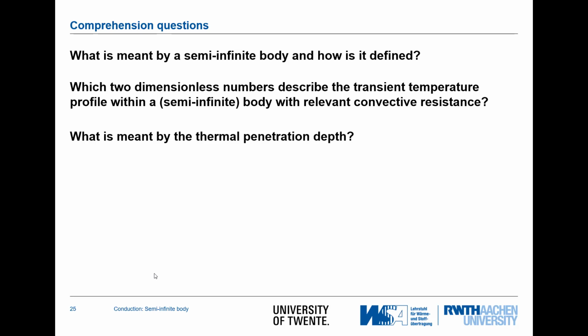And that means that the body is either thick or the body has a relatively low thermal conductivity. And from that, we can then calculate the penetration depth. And if the penetration depth is lower than the body thickness, then we are, of course, safe with a semi-infinite body assumption.